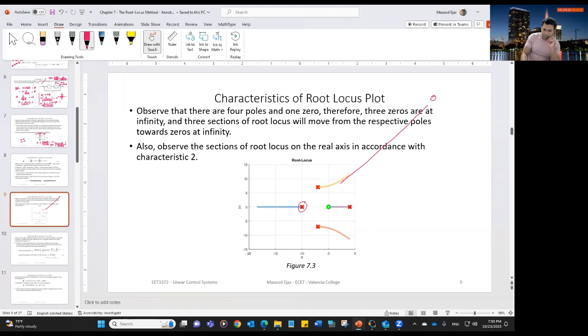And the pole that is sitting at s equal to -10, the loci from this pole start heading towards infinity, with the zero that is sitting along s equal to -infinity. So this Root-Locus has 4 sections, as you can see. When you start changing the value of k and start accumulating the values of all the roots and start connecting them through a line, then you will get these 4 sections of the Root-Locus.